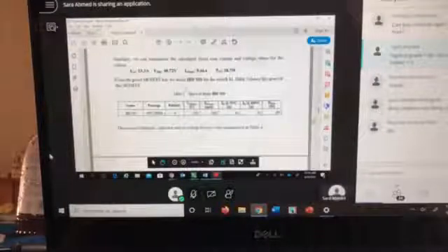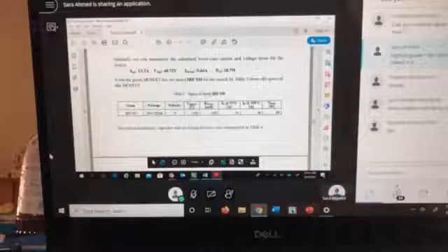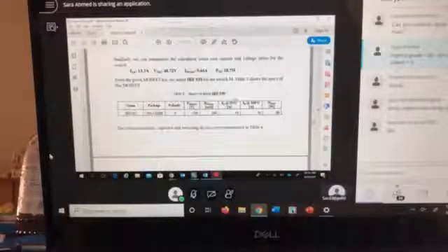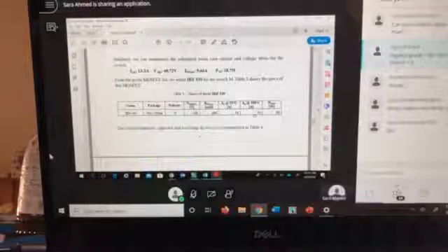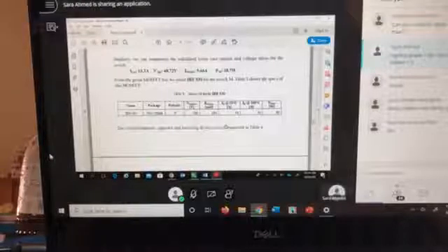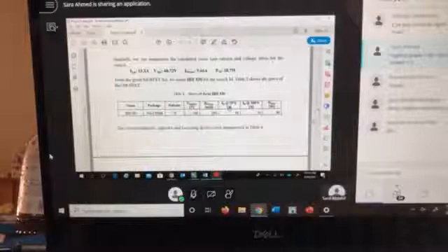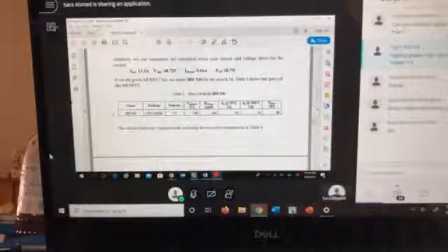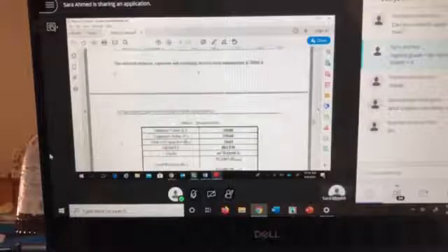So what are the 2 columns you're looking at? You're looking at your voltage column and you're looking at your current column. And we said only worry about your 25 degrees centigrade because it's giving you the 100. Because if you remember, somebody asked in class and we said, worry about this 25 degrees. So it's basically 1.5 times the current. Okay, so this you selected.